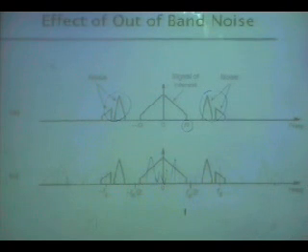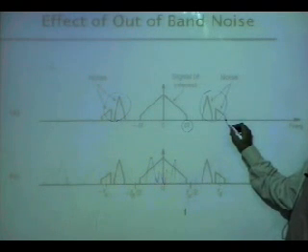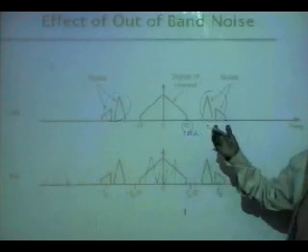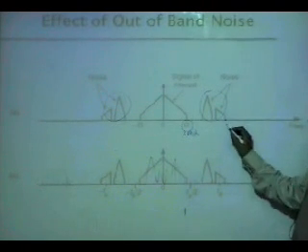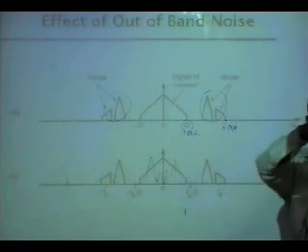So you need to clean in two ways. Either you use perfect analog circuitry, or you say, no matter what I do, there will be out of band noise, so I will cater for it. Let's say here it is only a 2 megahertz video. You say, no matter what I do, I am going to have things till 6 megahertz, because analog circuitry does not have a perfect cutoff.